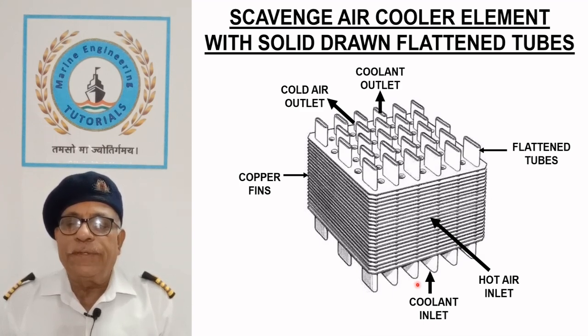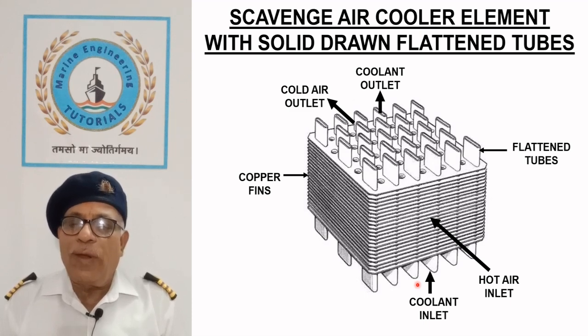On modern ships, central fresh water is used as coolant for removal of heat, which obviates the need for frequent cleaning as in the case of a seawater system. Low temperature cooling water requires regular treatment to maintain its alkalinity.